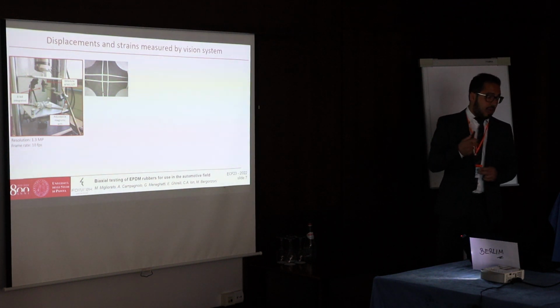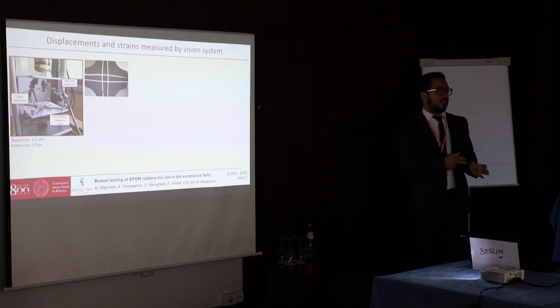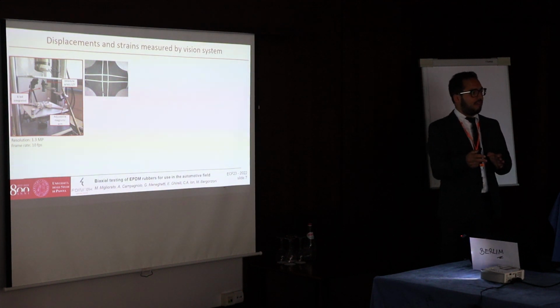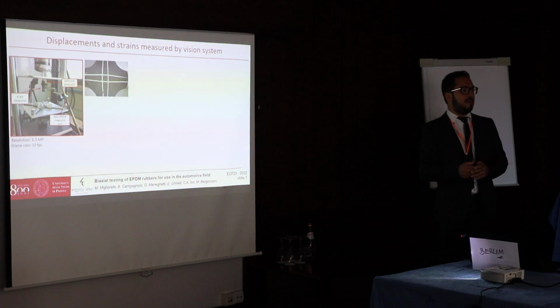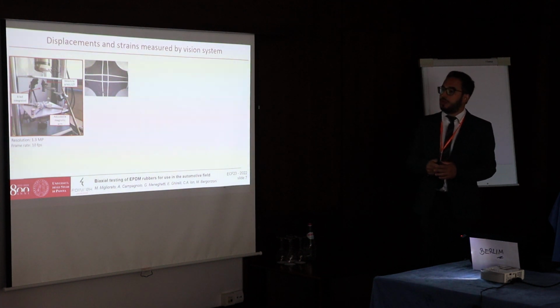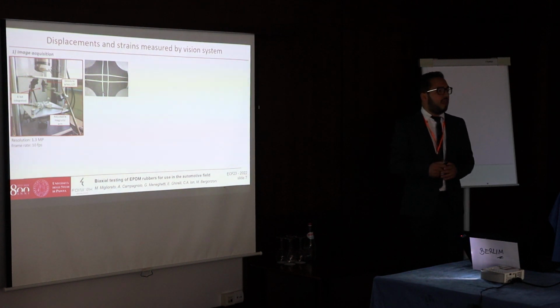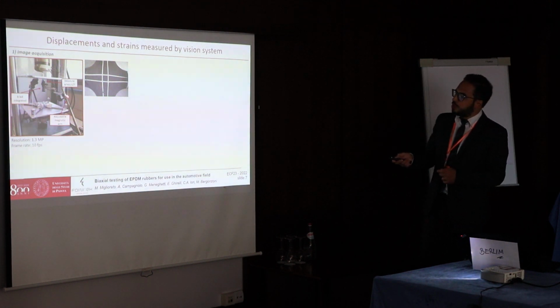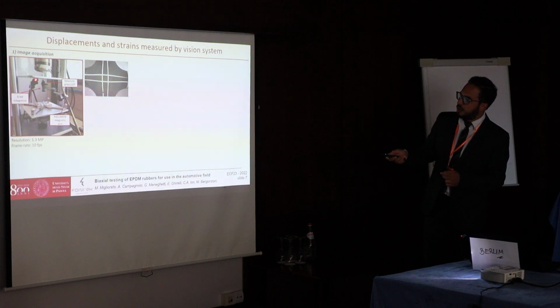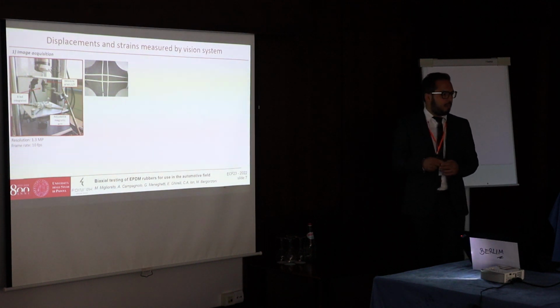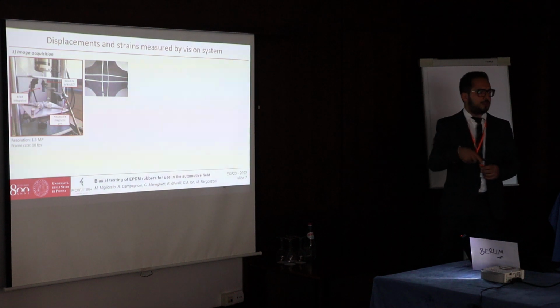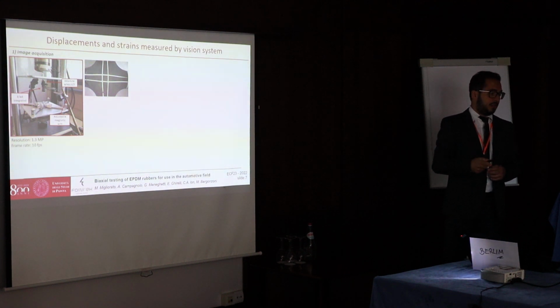After that, the procedure to measure strains and to link them to relevant stress levels has been performed according to three different steps. The first step is the image acquisition, which has been performed by using a digital microscope placed above the sample to measure the central area of the specimen during the full test.